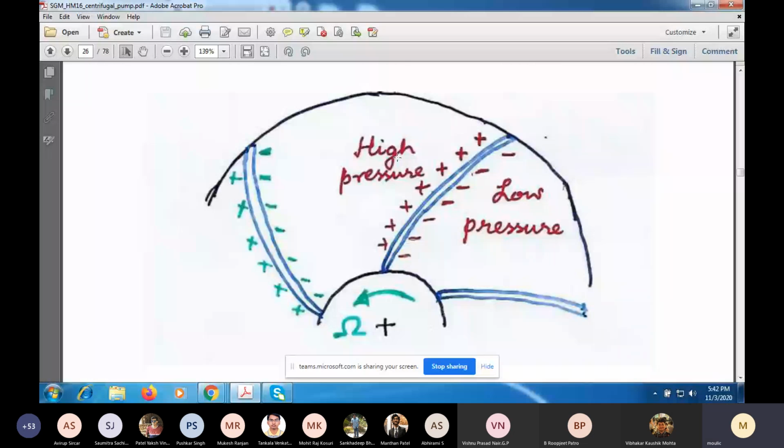So this is another blade. The plus signs indicate that there is high pressure on this side of this blade and low pressure on this side. I've used different colors here, the red for this middle blade, green for this blade here. Now look at this region in between. There's high pressure here and low pressure here. So the flow will not be one-dimensional. Relative to the rotor, there may be some recirculation here inside, which we are not accounting for in this simple analysis.